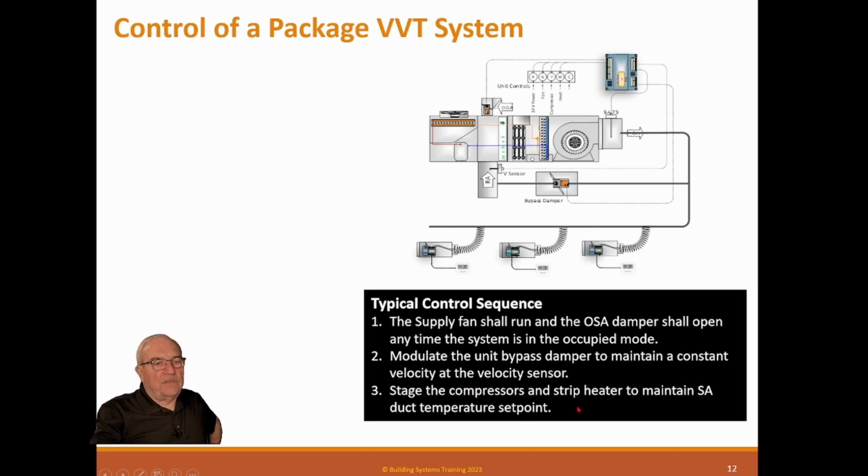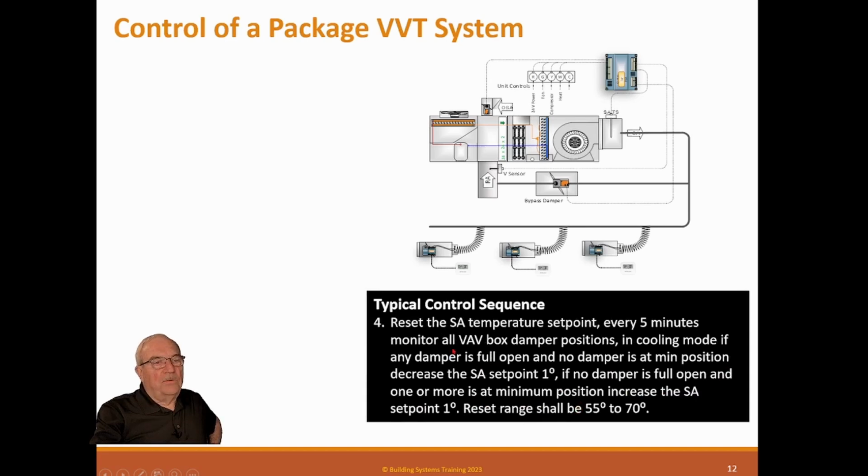Stage a compressor and strip heater to maintain a supply air duct temperature set point. Reset the supply air temperature set point every 5 minutes. Monitor all VAV box damper positions.